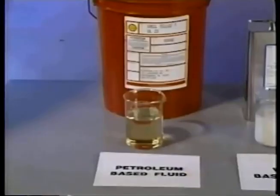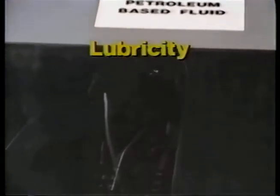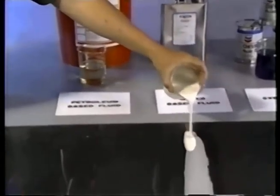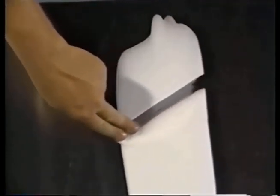Fluids that lubricate systems properly will have two important characteristics: good lubricity and the correct viscosity. Lubricity refers to a liquid's ability to form a durable fluid film between surfaces. For example, petroleum oil has good lubricity. It forms a relatively thick film, and it adheres to a metal surface well. Water-based fluids, however, do not generally provide as much protection as oils or synthetics because they are not as thick, nor do they adhere as well as petroleum oils.